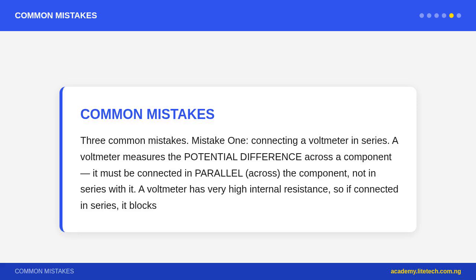Question 3. Wire color codes in a 3-core Nigerian electrical flex. What does each color mean? Brown equals live; it carries the voltage from the supply, the dangerous conductor. Blue equals neutral; it returns current to the supply, normally at or near 0V. Green/yellow equals earth, the protective conductor, connected to the ground; it provides a safe path for fault current to prevent electric shock from the metal casing.